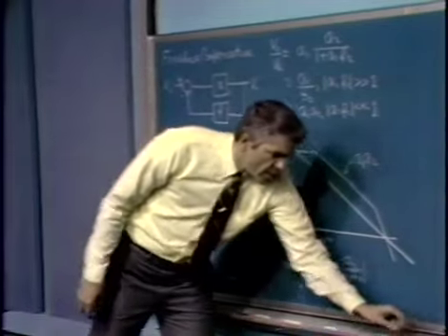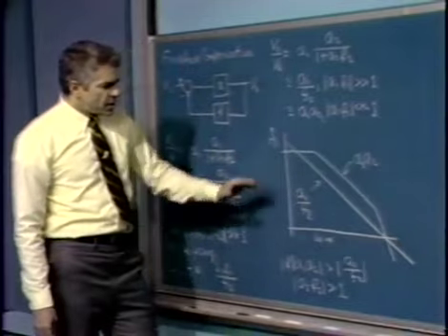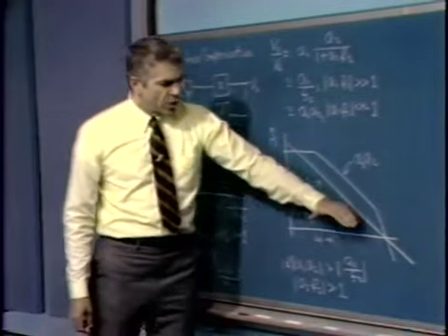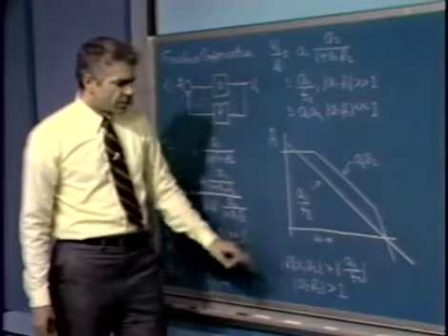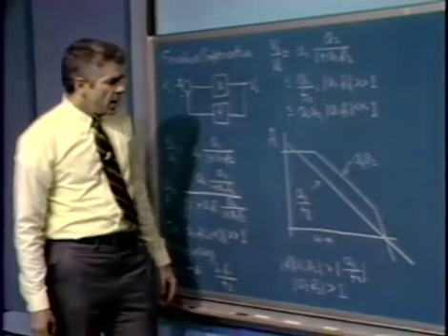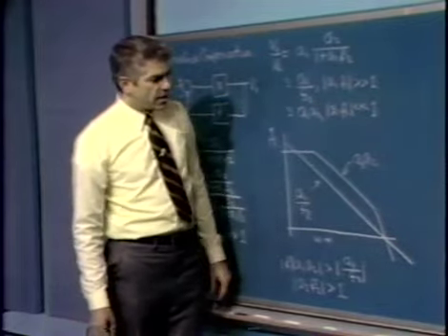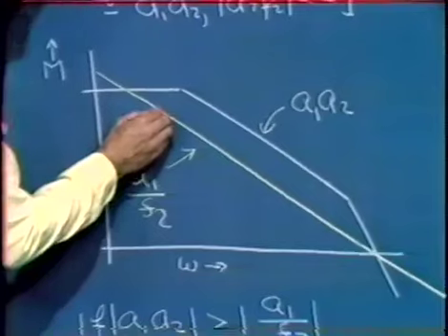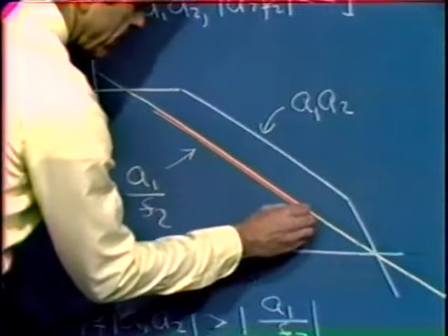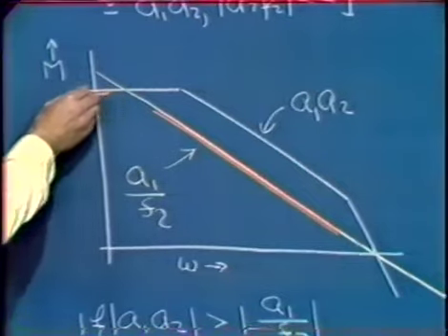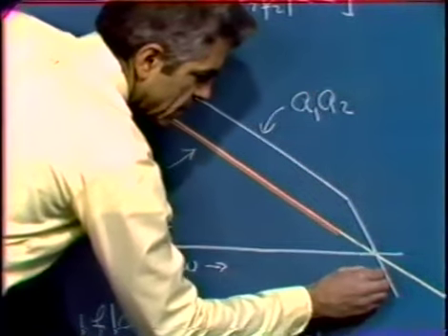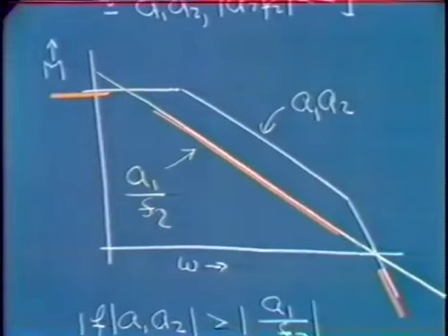Well, a very simple way to do this is to simply use the lower of these two curves at all frequencies. That's a consequence of simply checking the inequalities. And so we conclude, at least where the much greater than and much less than conditions were satisfied, for example, in this frequency range, and in this frequency range, we could simply select the lower of the two curves as being a very good approximation to the forward path transfer function of our overall system.